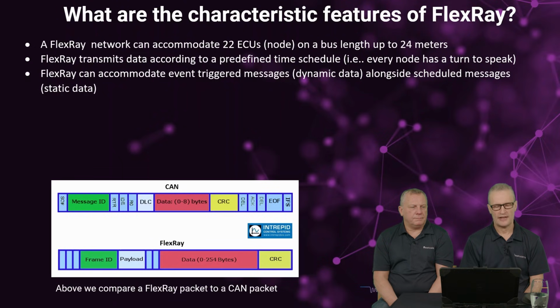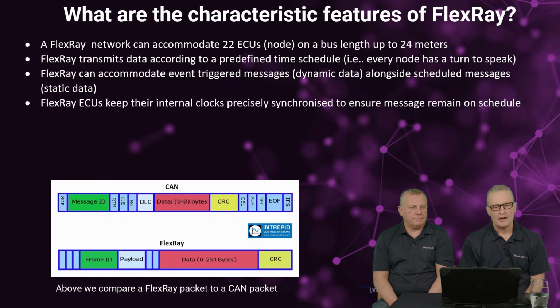Plenty of room on the FlexRay bus. FlexRay ECUs keep their internal clocks precisely synchronized to ensure the messages remain on schedule. We have got to have tight synchronization here when we have an event-triggered event. Everything has got to be perfectly aligned. So there are sections within a packet that ensure this timing is absolutely rock solid.